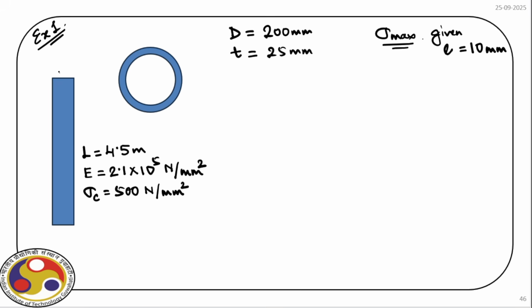So we have hinge boundary conditions, or let me apply hinge using this notation. So we have point load P, but this P is having some eccentricity. So this is the centroidal axis, and we have load P acting somewhere here.